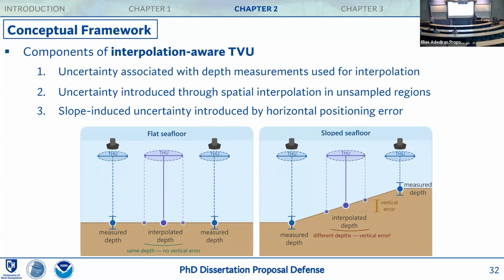So that's what's been giving me sleepless nights, because that's a major part of CUBE, which does incorporate the horizontal uncertainty into the vertical uncertainty. But what I'm saying is that for the measured depth itself, the total horizontal uncertainty independent of the CVU doesn't exist. It does not exist. Because it's been propagated, the vertical has been inflated to accommodate the horizontal. Yeah, and originally too much.